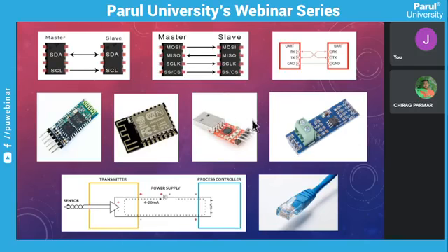Next is the USB. You're very familiar with this sign, that is USB. The USB communication is also very fast, very fast compared to all of these. There is a chip, the CH340G, a USB to UART converter chip. So a controller is connected here through UART, and any dedicated system like a computer is connected here, and UART is connected here.